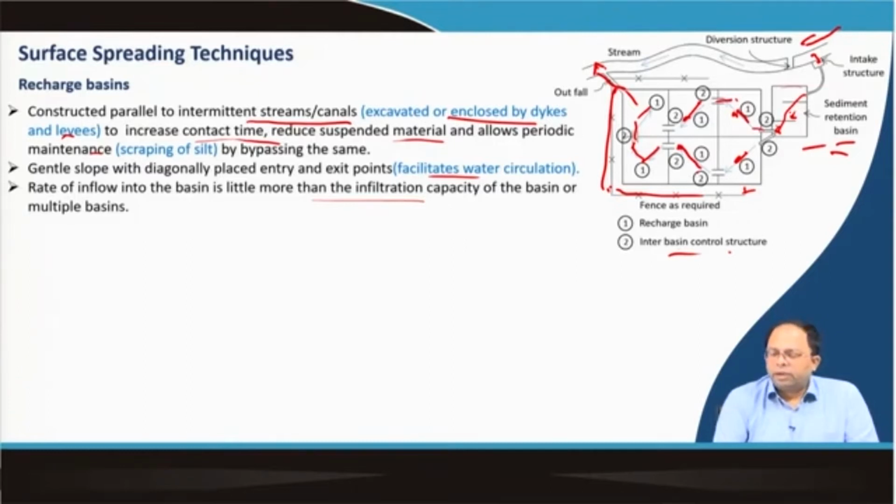And what we can do is, as there are two flow channels, we can use one flow and stop the other, and then we can clean that side, and when this part is clean, we can do the other one. Cleaning means if there are lots of silt deposits, after certain time periods we have to clean it. That means you have to scrape it and remove the silt.